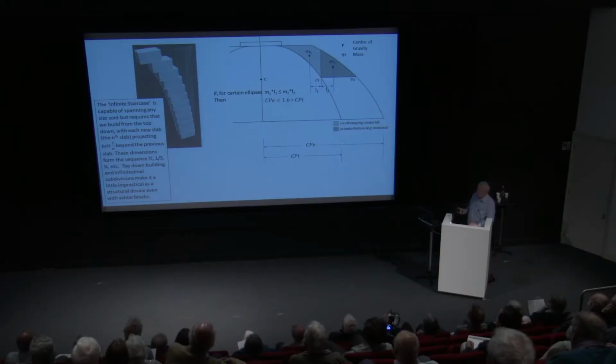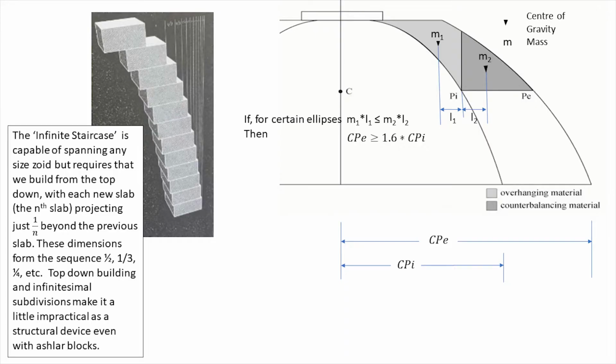Here's the principle of corbelling in brief. The downward force exerted by that mass out there must be equal to or preferably less than the downward force exerted by that mass in there. Otherwise, from that point, that mass will fall in.